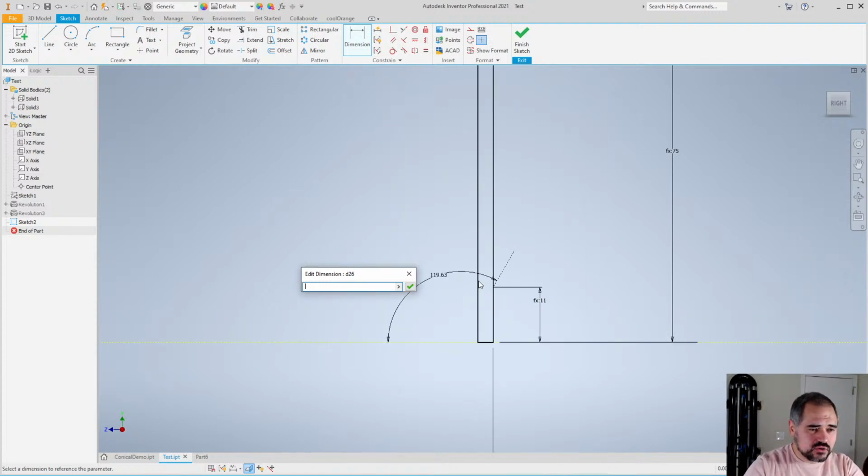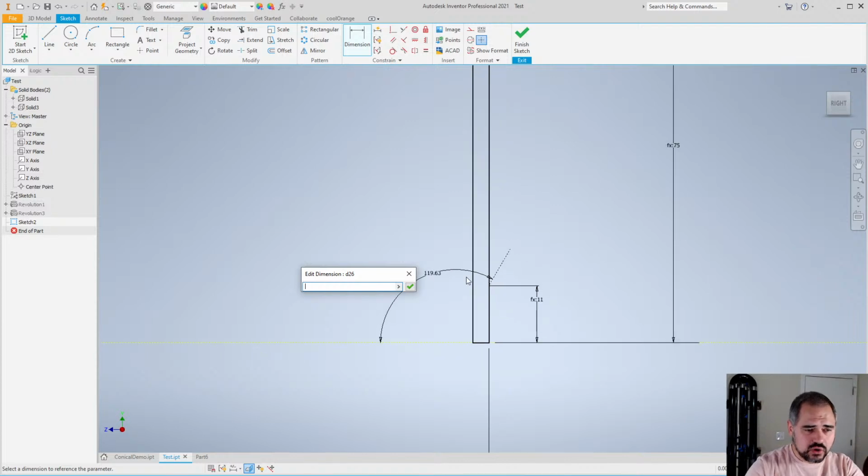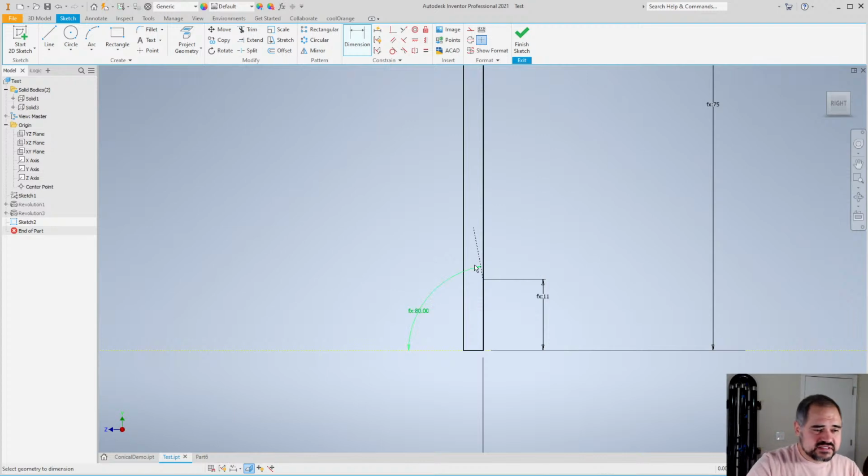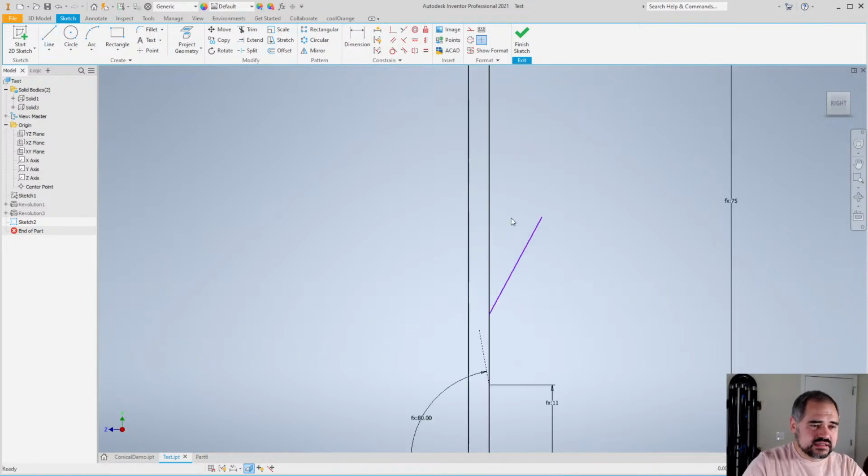We're going to set this angle to our tone hole angle. In order to do that, we're going to say 90 plus tone hole 1 angle. Since we have this angle set at -10, it takes 90, subtracts 10, and equals 80. You might wonder why we can't set this angle instead, so we don't have to subtract it from 90.